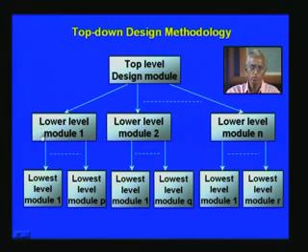So like this you can go step by step into different modules and keep on developing those modules. At every stage, naturally, a good practice will be to have a test bench for every module, whether it is this module or this or any other module, or even an intermediate one. If you have a test bench, you can rest assured that it will work right on the top when you integrate all the modules.